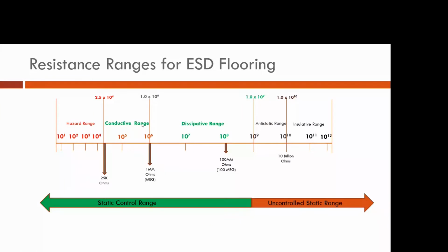If you're not dealing with high voltage, there is no fear that your applications are going to become so conductive that you could, heaven forbid, electrocute somebody by having conductive flooring. If you're going into that range where you're dealing with high voltage, you'll know what your specifications are, and in general, the flooring that you're going to be working with is insulative.